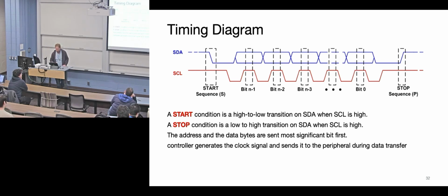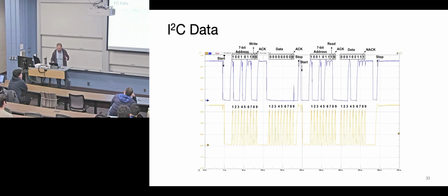Okay, so that addresses the bit. And then as you saw in your lab, oftentimes there's multiple packets that need to be sent, because your peripheral may have registers in it. This is the physical, PCB-level instantiation of memory mapped I/O, where you have this peripheral out there that needs to be reconfigured, and you're going to send packets into its registers, and that may take multiple data cycles to let that happen.